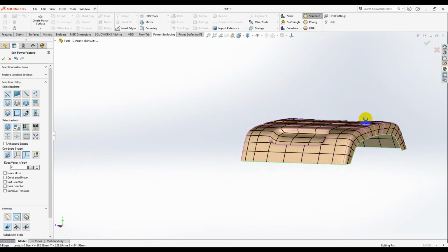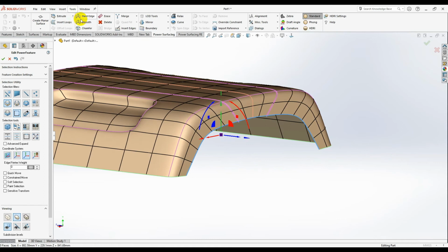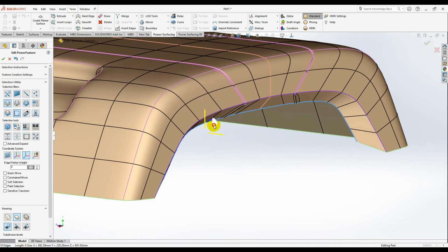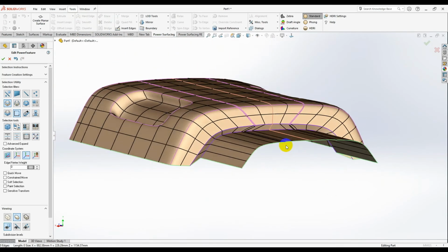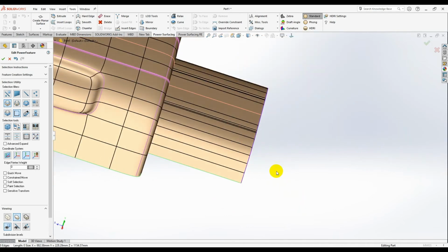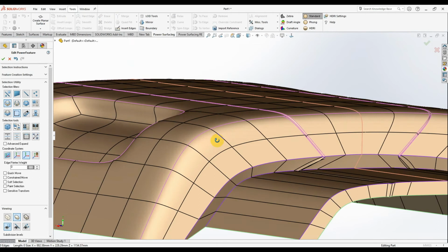As you see here, from this side you can also create a hard edge by pressing the hard edge here and snapping inwards, hard edge again and snapping out like this, and do the same like this and down. As you see, I just created more snaps.